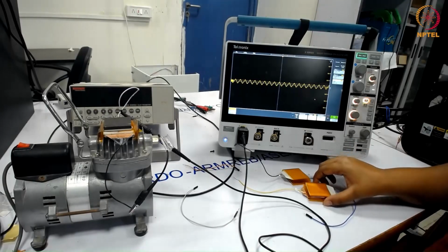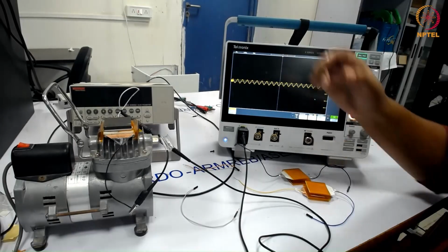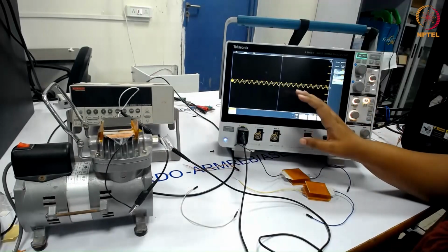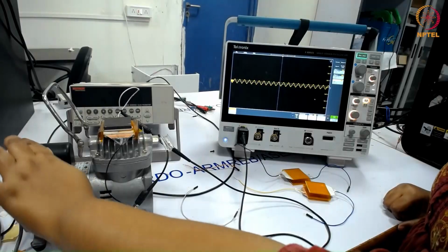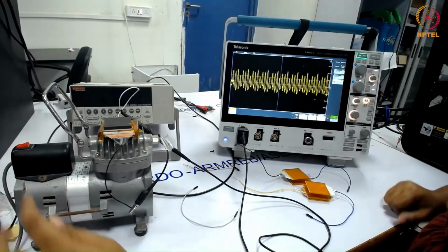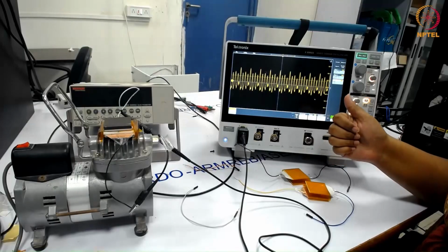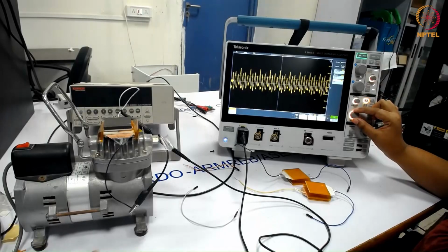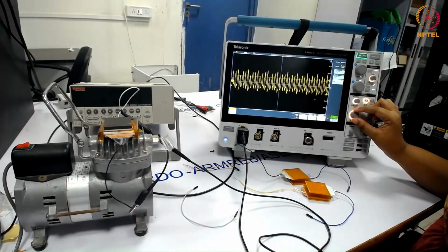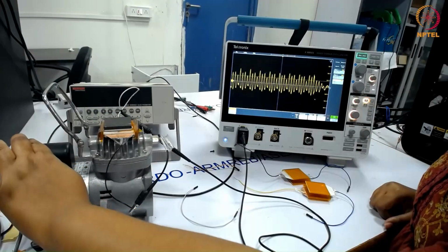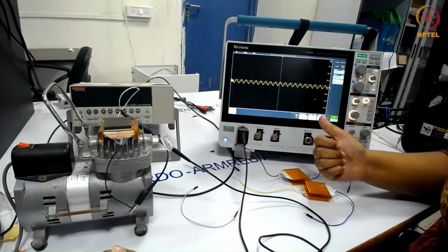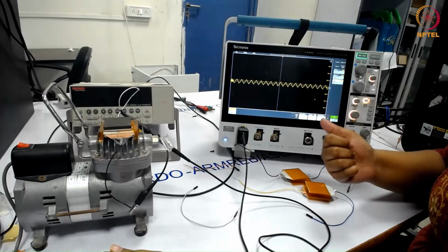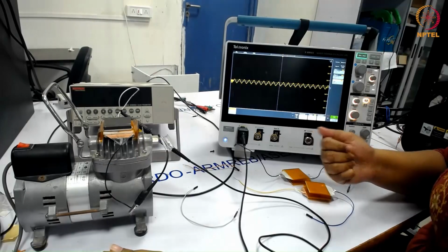Now, to demonstrate the sensing capabilities of TENGs, we have mounted one TENG over an air compressor. Initially we are getting some minimum noise. As we turn on the air compressor, you can see that voltage signals are generated corresponding to the vibration generated by the machine, which is detected by the TENG. And as we turn off the machine, we are not getting those voltage signals, which shows that TENG has the capacity to detect the working condition of any machine.